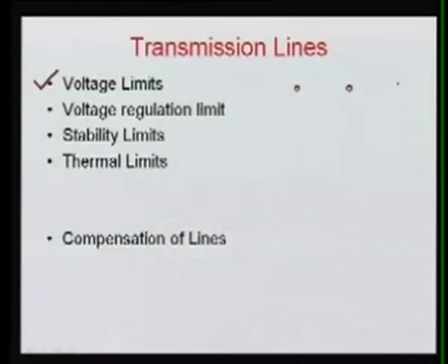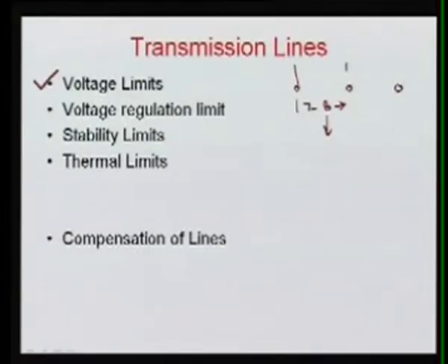The reason behind that is that we would need more right of way. Right of way here means the spacing between the 3 conductors, which is normally 7 to 8 meters even for lower voltage, and sometimes goes up to 15 meters. So, if you go for more and more voltage, this spacing will keep increasing, and finally it will be very uneconomical, because you have to go for very huge towers and the cost will be very, very high.